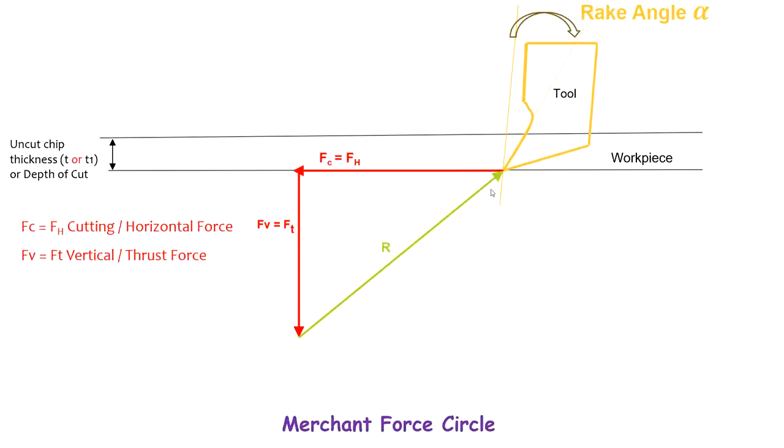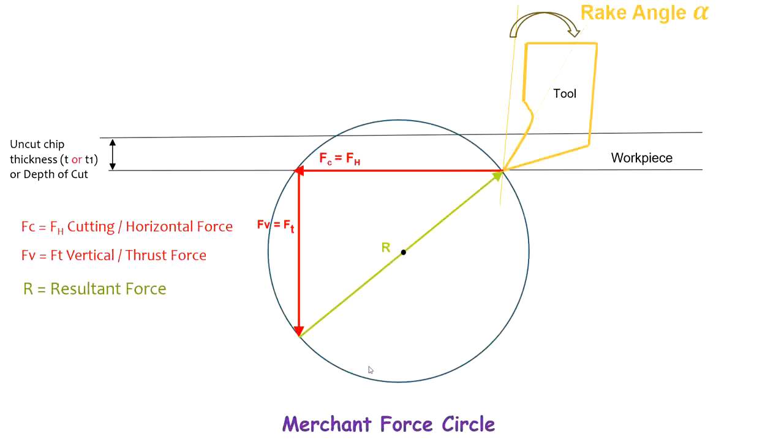We can draw one circle by considering R as a diameter, or we can find the center point of the segment R and then make one circle. Now this circle is the Merchant force circle. Thrust force is important because it will hold the cutting tool against the workpiece. Therefore, this thrust force is an important one.